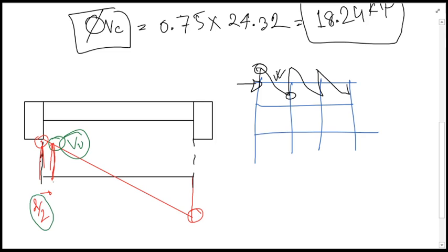After d by 2 you will be getting this particular distance, the maximum value of shear you will be considering, and while considering this VU, all the VU values you will be putting in the table for each of the beam, so that you are not only getting it for one load.